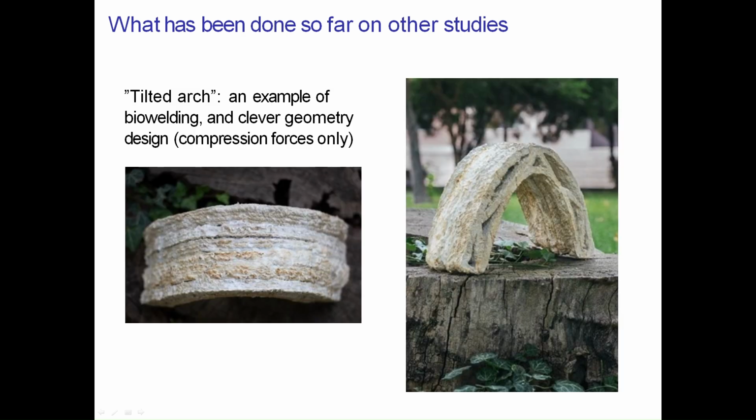The second important study is that of Modonlu and others with the title Tilted Arc. This study focuses more on structural design strategy rather than creating a stronger mycelium-based composite. This is a proof of concept study for a load-bearing structure. Mycelium-based composites are weak in tension, as we saw earlier. However, the arc design bears load only through compression, working around the material's weakness.